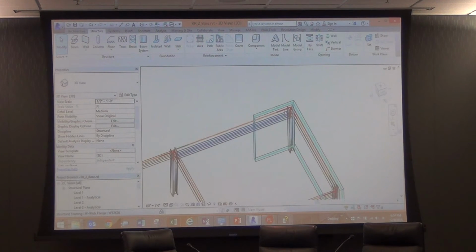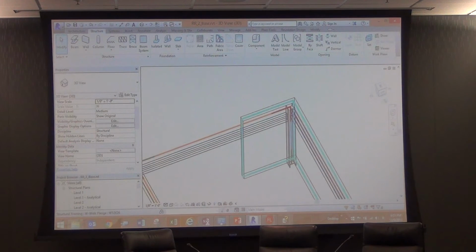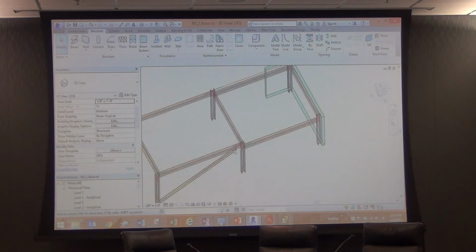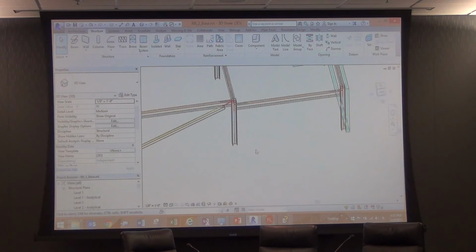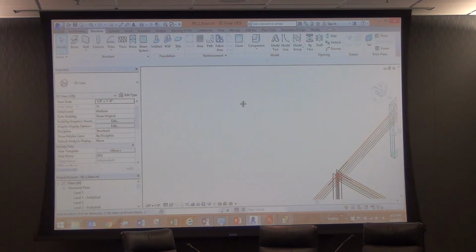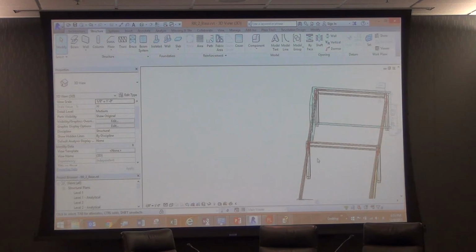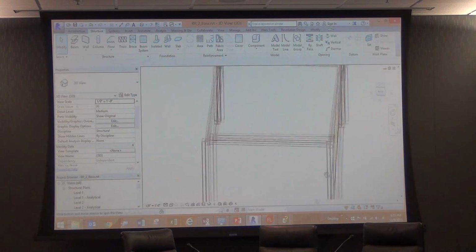In that situation, you do want the center line of that beam to be out further, in line with your beams, rather than moved in with your columns. And then here, what I wanted to show is a couple of different situations with these beams. What I had done here, I think I rotated the axis of one of these.